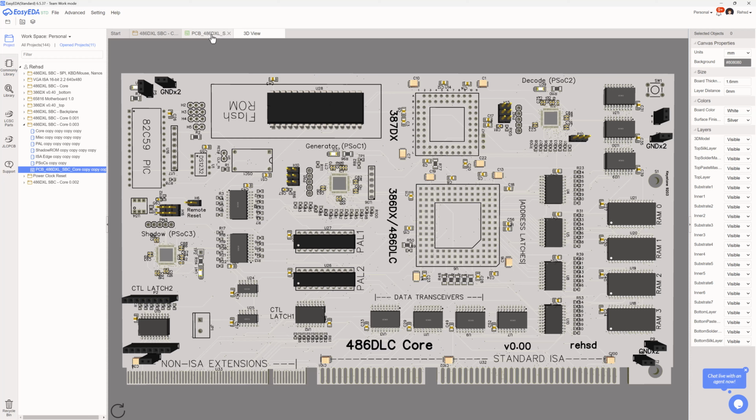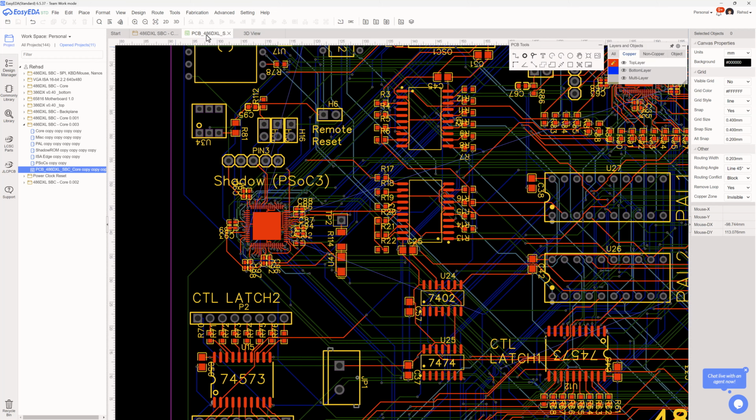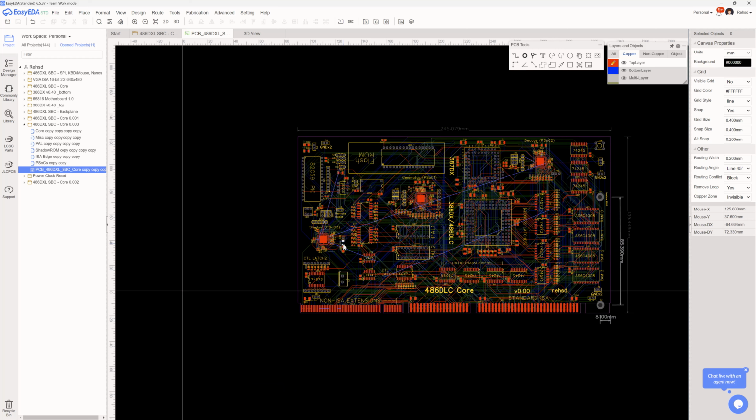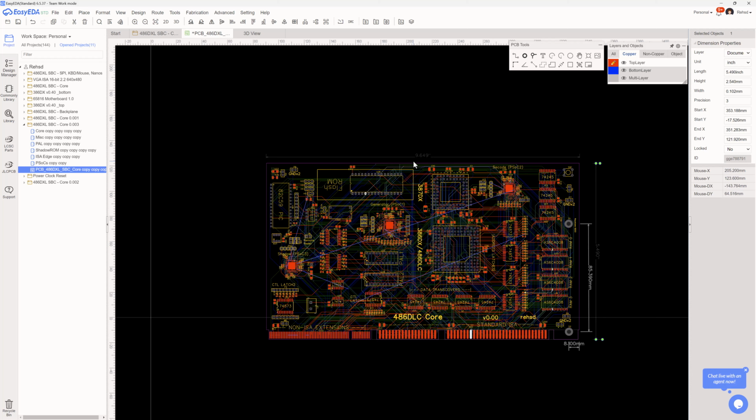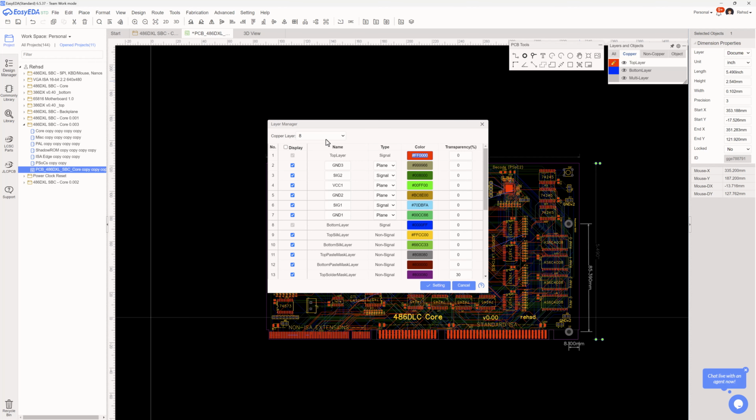And if I go and look at those dimensions real quickly, you can see I'm looking at about 245 millimeters by 139. So I'm at about 5.5 inches by 9.7 inches. So the board is reasonably sized. It still ends up being, at least the way this is set up, an 8-layer board, which is where I have it right now. It's still about $120 for this set of 5 boards.